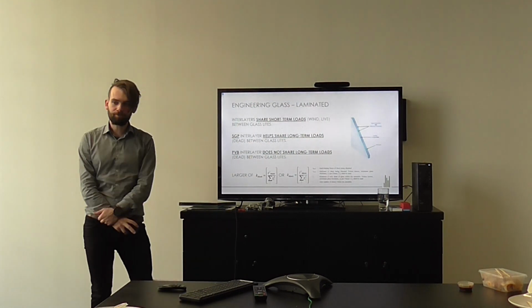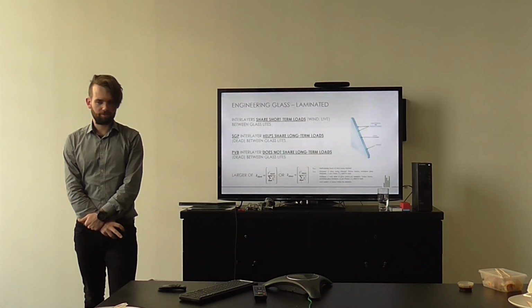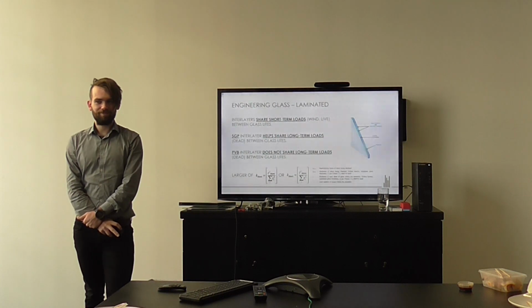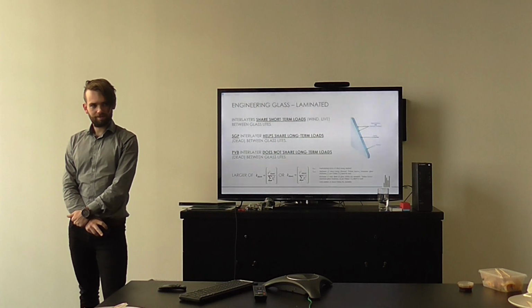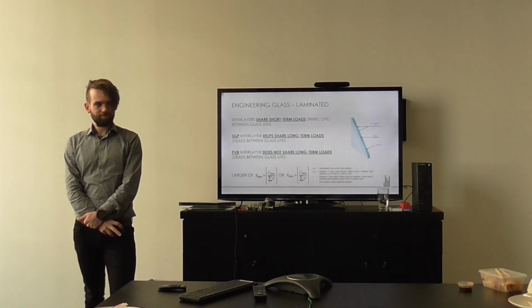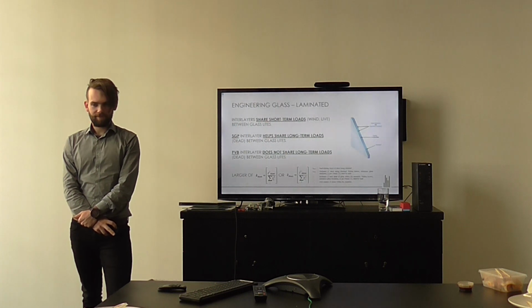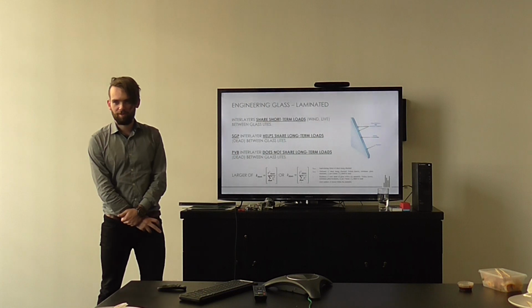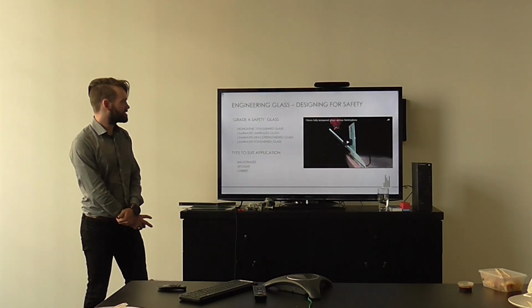What does SGP stand for? Sentryglas, DuPont. It's actually like calling a tissue a Kleenex. It's a brand name, so the generic term for that type of interlayer is called ionoplast. There's very few people who make it, so we tend to use DuPont's product, which is called SentryGlas Plus. Again, there's some knowledge of operations here at the bottom, not really all that fun or useful, but yeah. So the next one I want to touch on is...